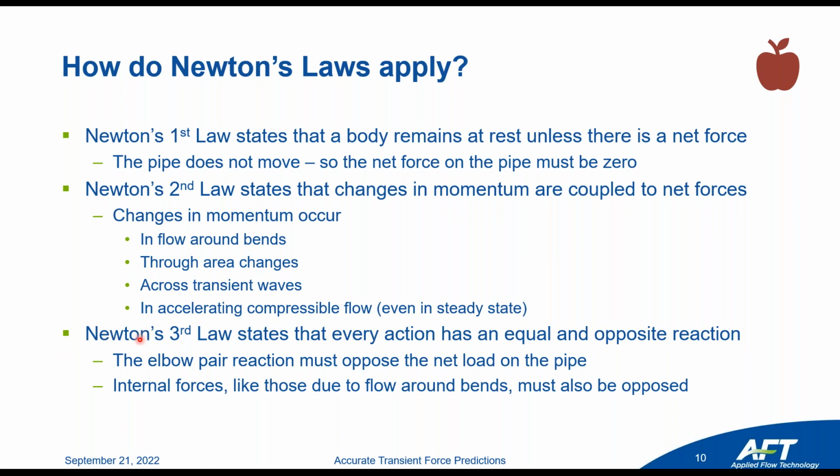Newton's third law states that every action has an equal and opposite reaction. So this elbow pair reaction must oppose the net load in the pipe, and internal forces like those due to flow around bends must also be opposed, and we'll use that internally to this method shortly.